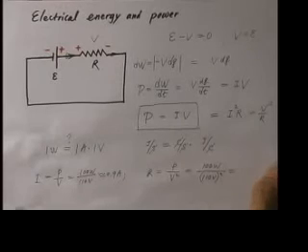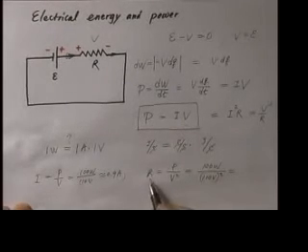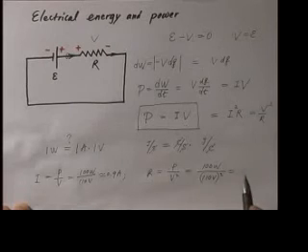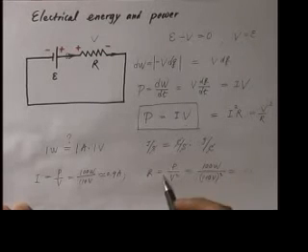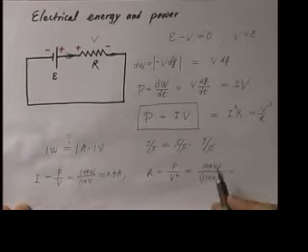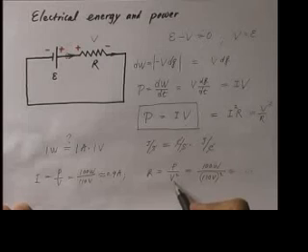That will give you a resistance of about 1/100th of an ohm. That will be the resistance of the tungsten filament, and you can calculate that for other incandescent light bulbs as well. As a matter of fact, if it's a 60-watt or 50-watt light bulb, you find that R is actually smaller because the power is smaller and the voltage is the same.